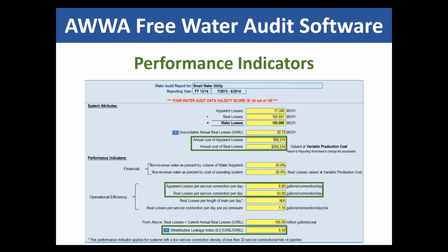That threw out the issue there with those big volumes, right? So I said, well, then let's use the software. Let's take a look. LA, how many service connections do you have? So they operate 700,000 service connections, and the other guy operates 6,000 service connections, right? So dividing 1 billion gallons by 700,000 service connections by 365 days, their real losses per connection per day are around 25 gallons per connection per day. So then I was asking the other guy, so where do you land? Well, I'm at 28. So now you can compare apples to apples, right?